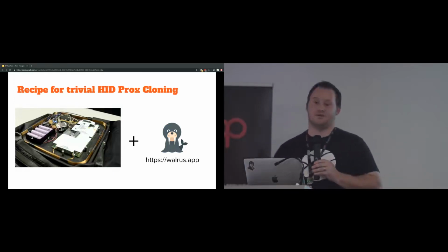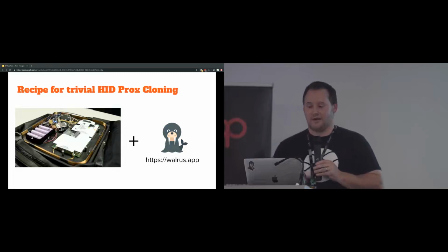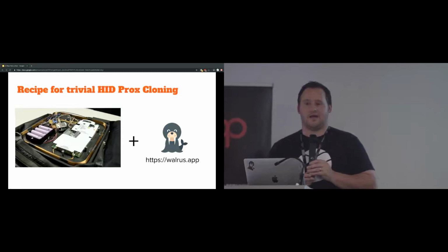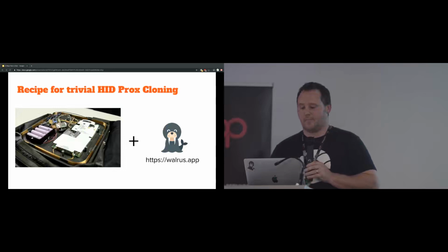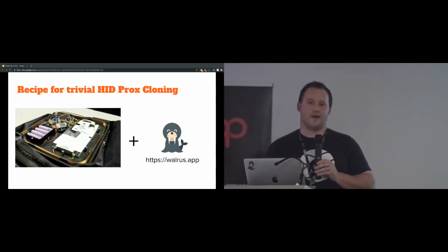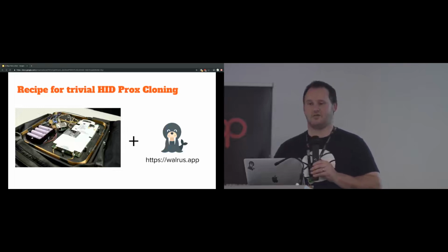It's an Android card cloning app that was developed by some of my very clever colleagues. And this thing in a laptop bag makes surreptitious cloning of HID Prox cards completely viable in the field. We get ranges of up to about 1 meter when cloning people, and that means you don't even have to get awkwardly close to them, you just have to walk past them. I mean, this is so well understood now, and the tools have reached that kind of maturity that this is just like commoditized ownage of it.